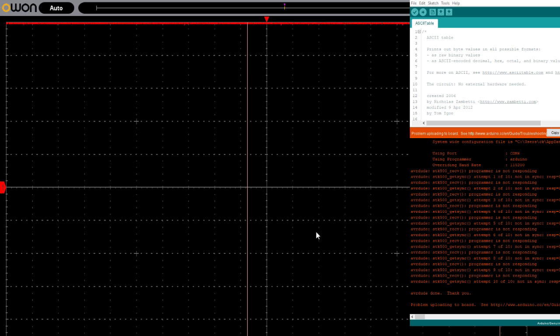Yeah, the FTDI has the 5-volt ground and then 3 pins that I connect: the reset and then the transmission and the receiving, which are flipped on the Arduino. So there's a total of five connected pins on the FTDI. Red for plus, black for negative, and then I've got the reset on orange that goes to the capacitor and then to the reset pin on the chip.